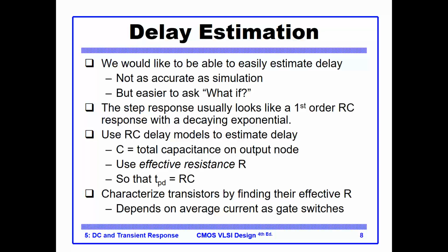And in the first part, we have established that circuit analysis and deriving solutions using current equations is somewhat complicated. So we will start with the first method of estimation, using the fact that we will remove the NMOS transistor and replace it with an RC circuit. Okay, so these are the kind of things we're going to do here.